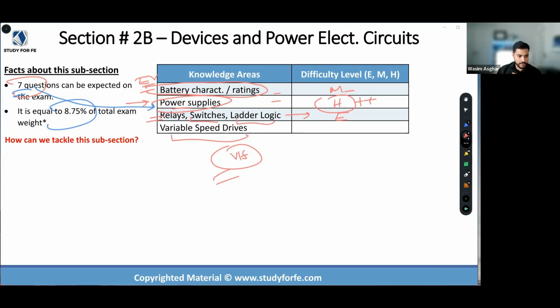So in the VFD section, we took a deep dive into scalar control. We went through the math, and through different variations for keeping the torque constant, keeping the power constant, and so on. So that was our V by F control. Then in vector control, I introduced the mathematical concepts of the Clark transform and the Park transform, and helped you understand how, when you have the DQ currents, you can decouple the torque and speed. So it was pretty advanced.